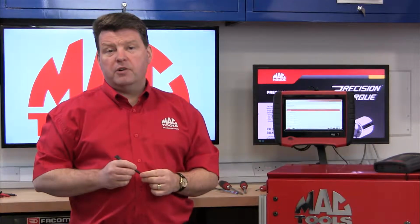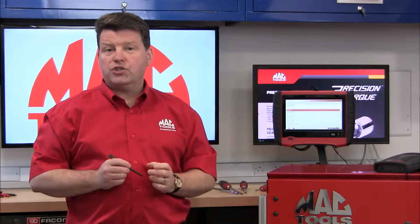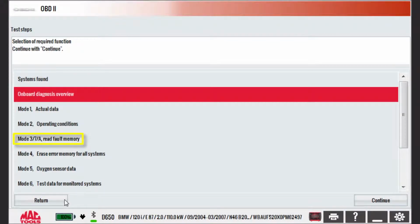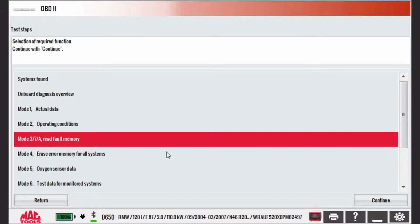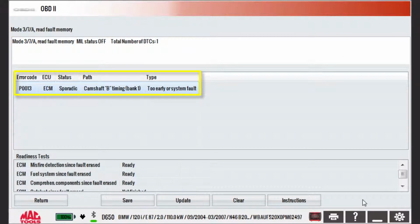I'm going to take a look at error memory first. The ET750 combines mode 3 for stored codes and mode 7 for pending codes as one list. Choose mode 3 and 7 from the menu, followed by Continue. At the top of the display, you're informed that the MIL lamp is off, with a total of 1 DTC or diagnostic trouble code stored. Beneath this is the error code P0013 stored in the engine control module. The code relates to the camshaft timing on bank 1.